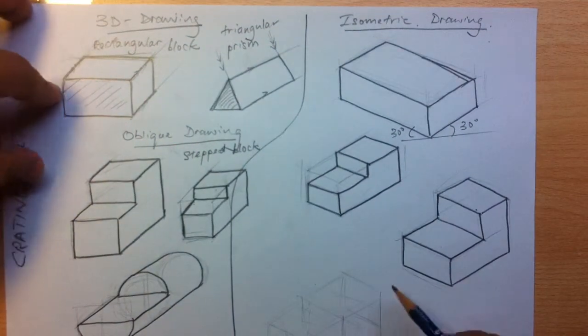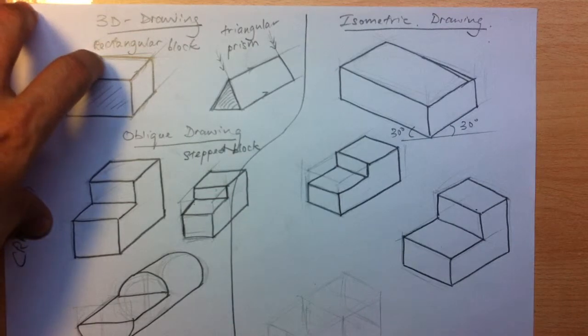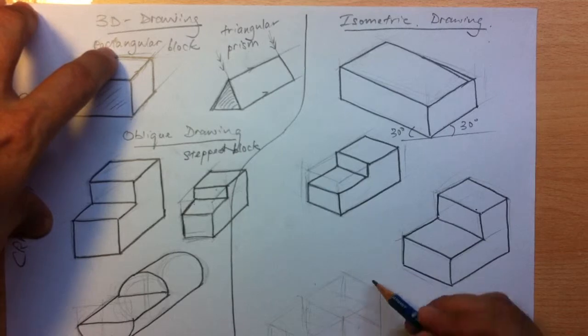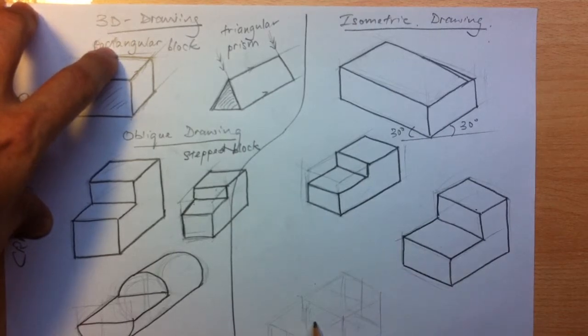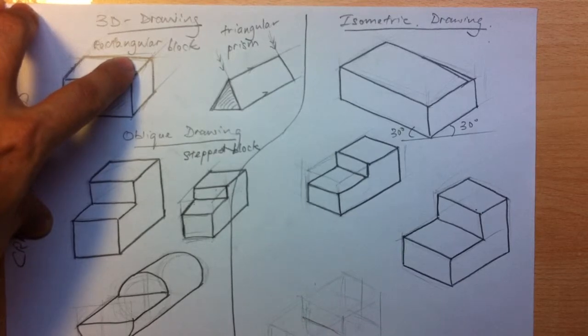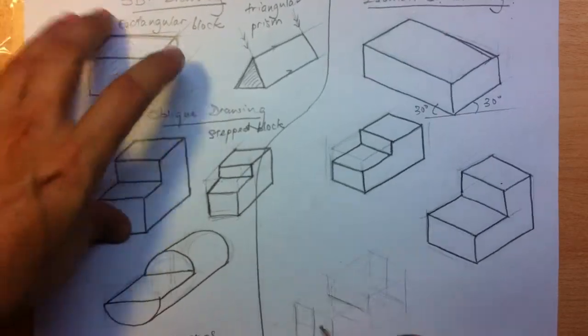Now at the bottom here, I have three square boxes that I've drawn at different steps. This is actually used to draw the round bar with steps, but it's in isometric form. Now remember the previous lesson. For a circle, we draw a square first, then we divide it in four. This is exactly how it's done.